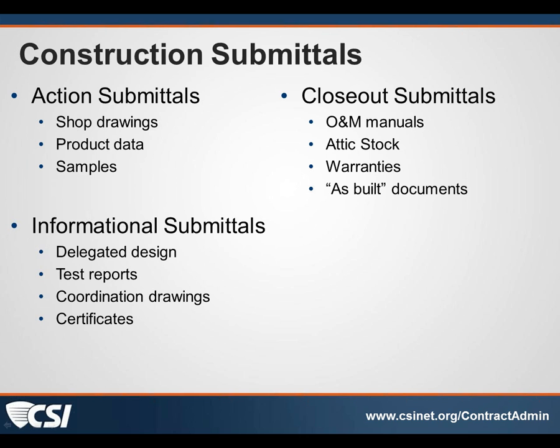Yeah, I'd echo that. I would strongly advise that you check as you're preparing the specifications with the owners to see what, if any, attic stock they want. These spec software packages typically include attic stock, and because it's in there, we leave it in. But a lot of times, in my experience, the owner doesn't have a place to put it, doesn't want it.